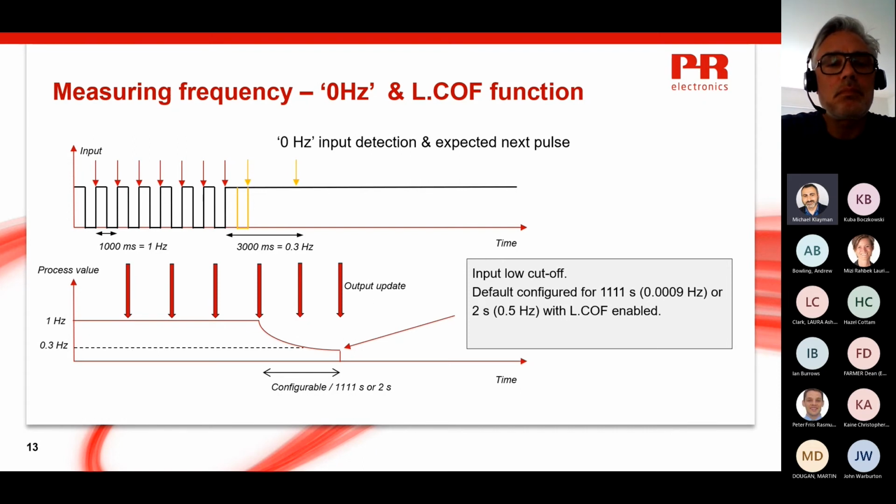Let's consider this situation. Let's say we have a flow meter that measures flow coming from a dispensing pump. We can see on a display that we are dispensing 1 liter per minute of liquid into our process. Our flow meter creates a pulse for every 1/60th of a liter, so a pulse every second. The dispenser pump is then shut off to stop the flow, but the display still shows a 0.2 liter per minute flow rate after a few seconds. Why? The graph here might help us explain the situation.